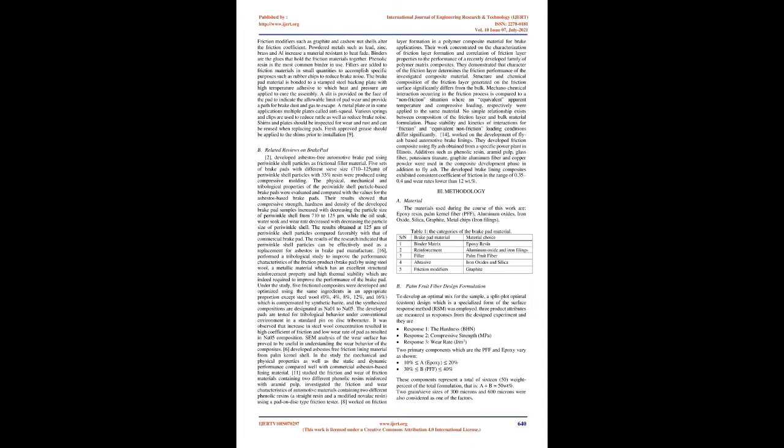2. Literature review. A brake pad. Brake pads are steel backing plates with friction material bonded to the surface that faces the disc brake rotor. It is one of the important parts of an automobile braking system due to its vital role. Friction between brake pad and disc converts the kinetic energy of the automobile to thermal energy. 2 brake pads are contained in the caliper, with their friction surfaces facing the rotor.